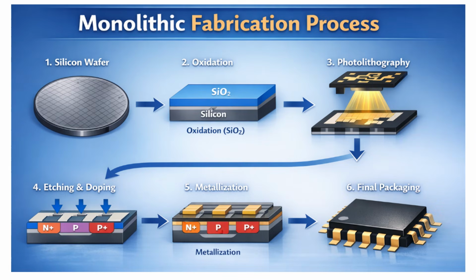Steps: prepare the silicon wafer, then oxidation, the second step, in order to develop the SiO2 layer. Then photolithography, where we use the photoresist. This is to develop multiple layers over the SiO2 layer, so you can develop as per your requirements. Further, if you have grown some extra layer, you can etch or erase it. That is called etching.